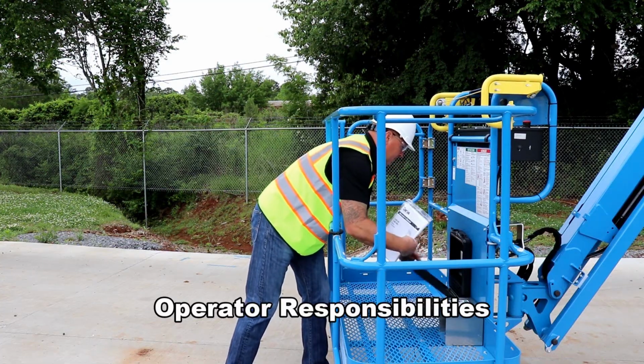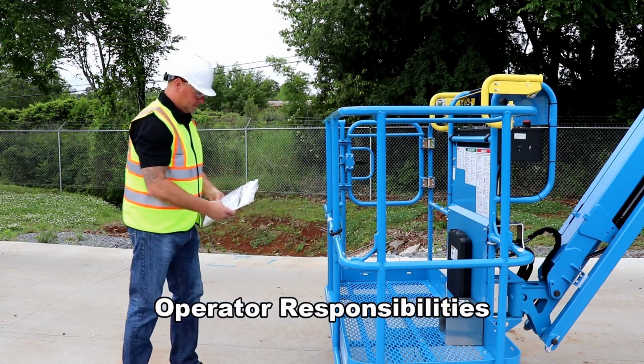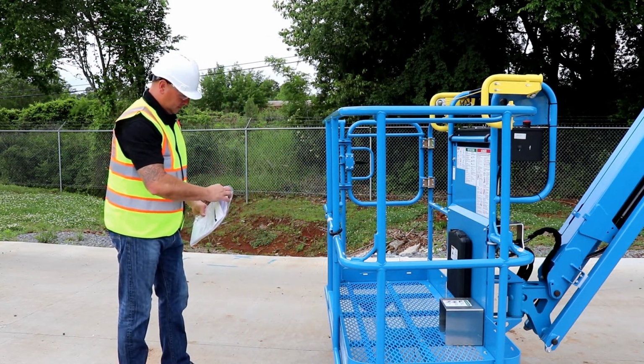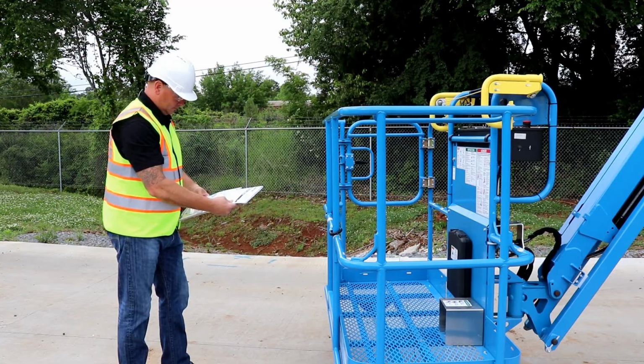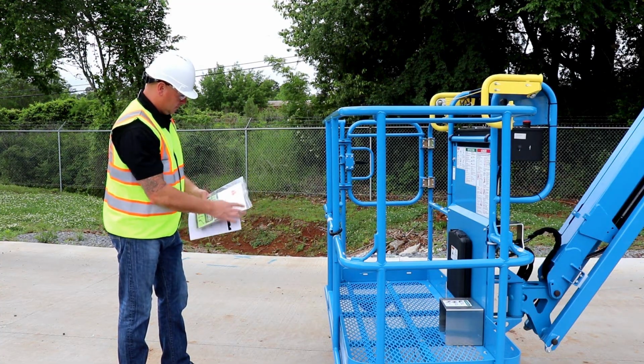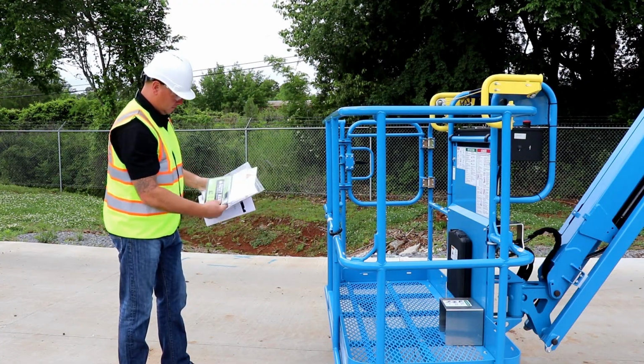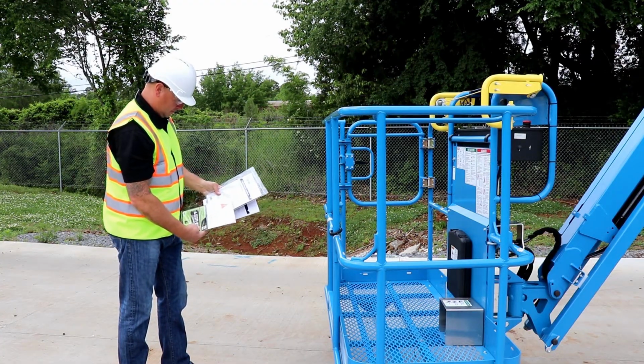The operator is the person who actually performs work using a MEWP. It is the operator's responsibility to check that the operator's and safety manuals are stored on the machine and are always read and understood before operation. The operator is responsible for operating the MEWP within the limits of intended use as defined by the manufacturer in the operator's manual and job site and government regulations.